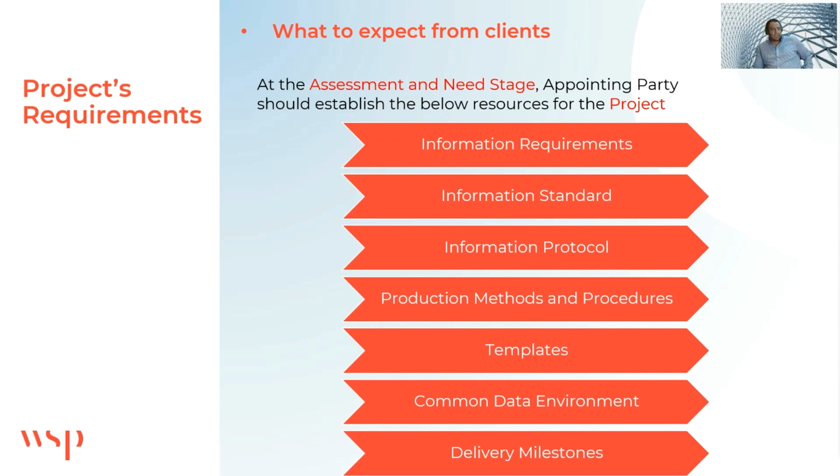So at the assessment and need stage, the appointing party should establish this set of documents, which is the project information requirements and the project information standards. And the project information standards are a bit different from the information requirements. To understand the main difference, for example, for the information standards, the client needs to define how the exchange of information will happen. What standardized element for exchanging information have been established for the project.